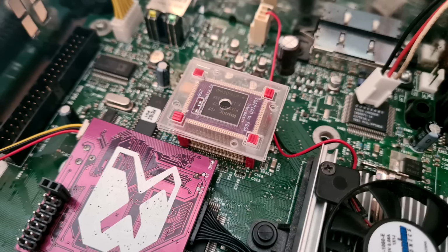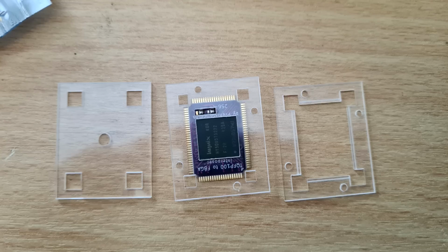In an attempt to fix the alignment issue, I made this. It's 3 layers of 1mm acrylic. The idea was that the middle layer can key onto the BGA. You see the square in the center is perfectly the same size as the BGA chip. And then this can provide the alignment that will get the pins aligned on the springed pins of the tester. I think this was a good idea, but it was flawed in 2 ways.